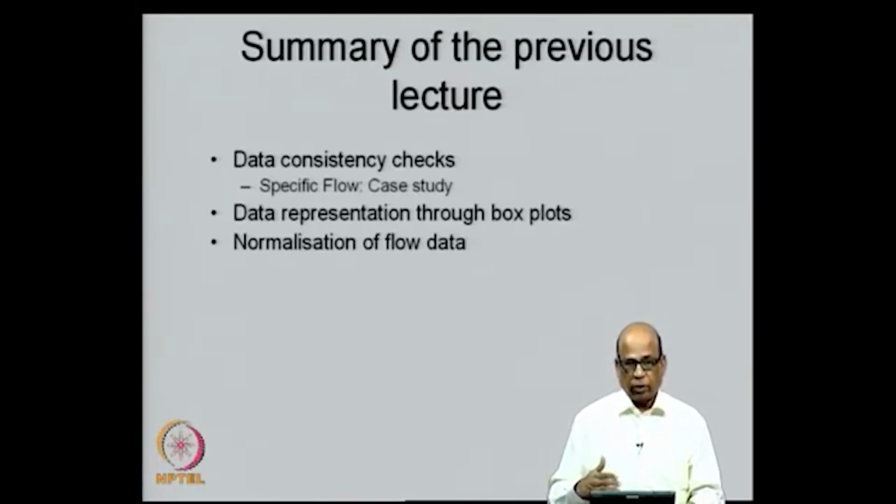Now, these box plots are useful especially when we are comparing different time series or the variability of a particular time series across different time windows. Let us say that you have a long time series of 100 years of flows. You would like to examine how the variability was in the first 20 years as compared to the next 20 years, and so on. So, these box plots are handy tools for examining such variability in the data.